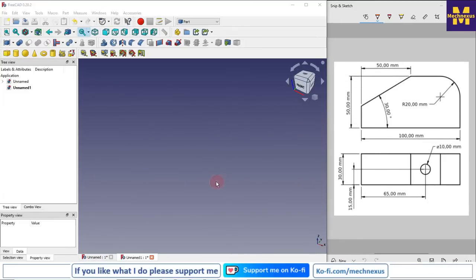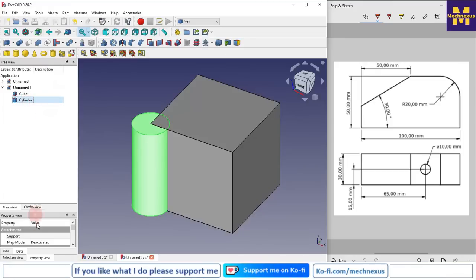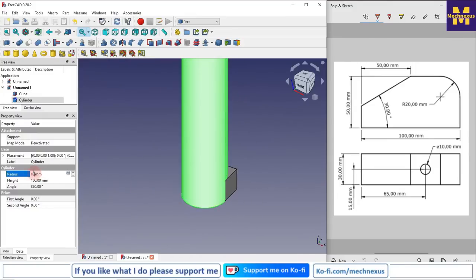Before starting this part, we will briefly see the core features of the Part workbench. So here are the part primitives. With the help of a single click we can insert a shape in our part. If I click on the cube, it gets inserted. If I click on the cylinder, it gets inserted, and we can modify its properties. For example, for this cylinder, if I want the height to be 100 mm, then I can simply change this to 100. Radius, if I want to change it to 10, then I can simply change it.